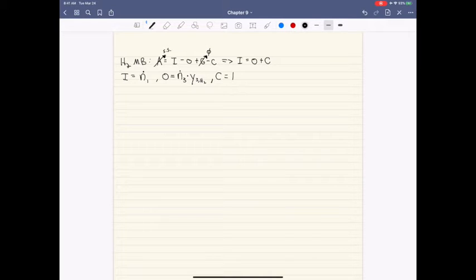And so the consumption in terms of the extent of reaction is going to be equal to the magnitude of the stoichiometric coefficient for hydrogen in our net overall reaction. And that's multiplied by the extent of reaction. Another way we could define the consumption term is in terms of the fractional conversion of the hydrogen gas. And so this is going to be equal to N1, which is the flow rate of the hydrogen gas being fed into the system, times that fractional conversion.